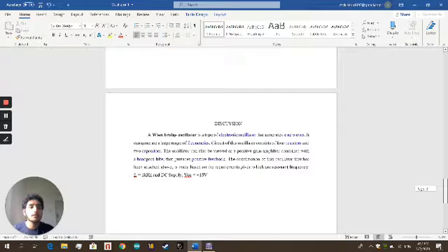What I can conclude and discuss for this oscillator circuit is that a Wien Bridge oscillator is a type of electronic oscillator that generates a sine wave. It can generate a large range of frequencies. For my circuit design and construction, I have included 4 resistors and 2 capacitors. The oscillator can also be viewed as a positive gain amplifier combined with a band pass filter. It can also provide positive feedback.